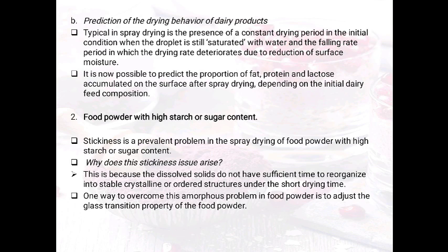Food powder with high starch or sugar content. Stickiness is a prevalent problem in the spray drying of food powder with high starch or sugar content. Why does this stickiness issue arise? This is because the dissolved solids do not have sufficient time to reorganize into stable crystalline or ordered structures under the short drying time. One way to overcome this amorphous problem in food powder is to adjust the glass transition property of that food powder.